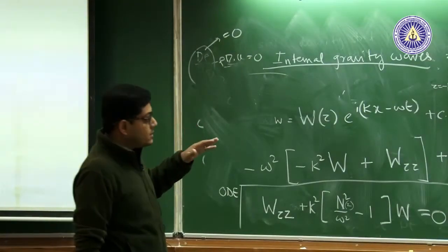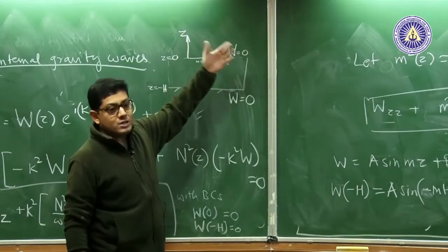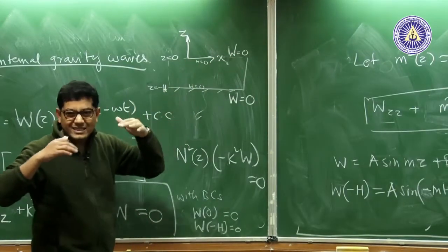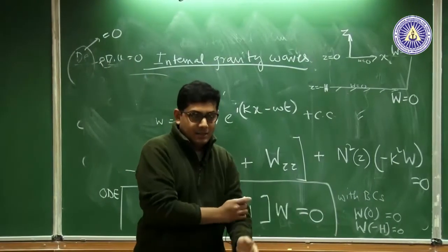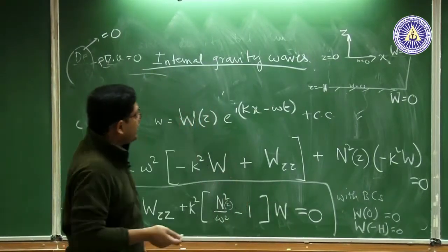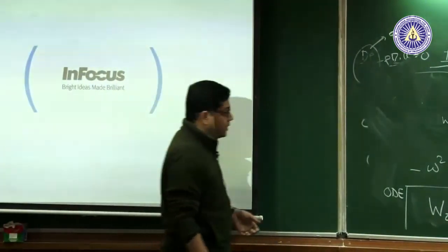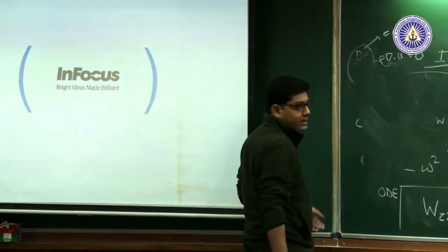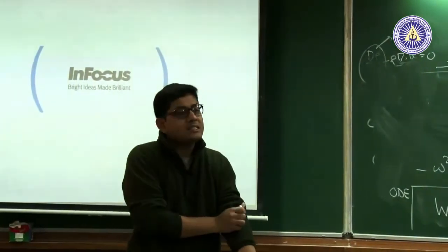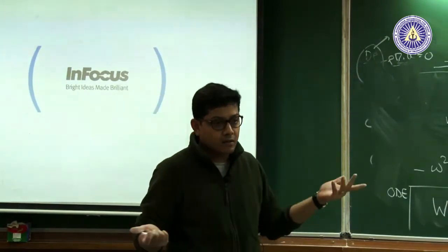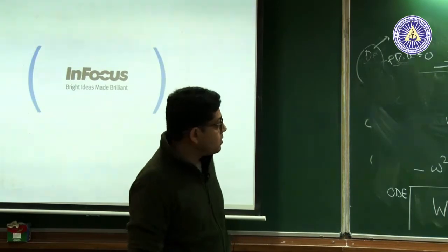The fact that internal gravity waves actually hit the free surface and produce something, it is technically not a rigid lid, but at order epsilon it is a rigid lid. So we have neglected the small terms. Usually we take epsilon as a steepness parameter, say Ka.